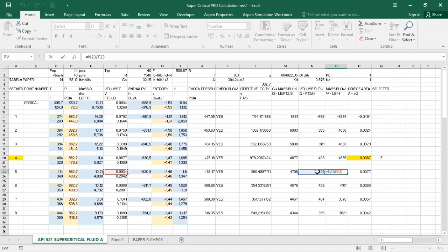That is very important because now you will not use the calculation based on the choked condition, but at the relief conditions. With mass flow and mass flux, I am able to do the calculation of the orifice that will take into account the KD, KB, and KC. So for the first iteration, I will do this procedure and I will have my table with the calculated area or the orifice for each case.